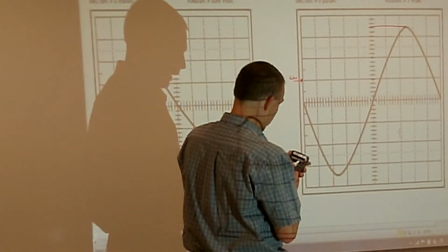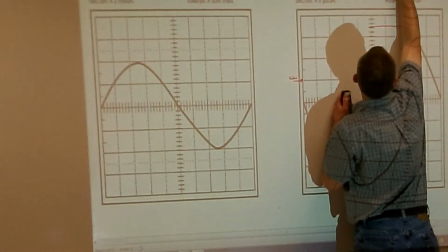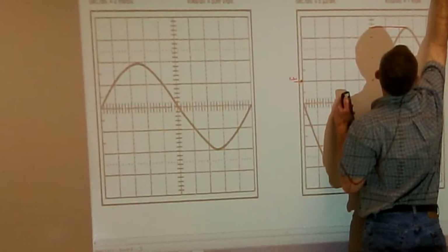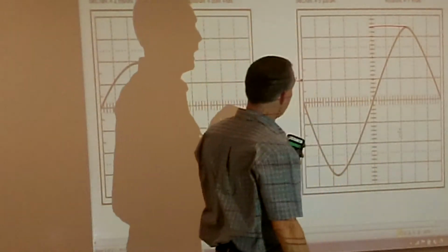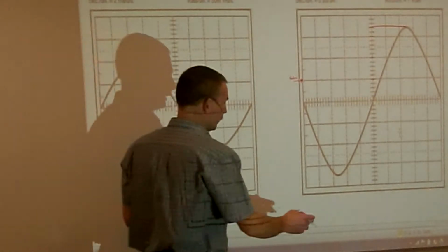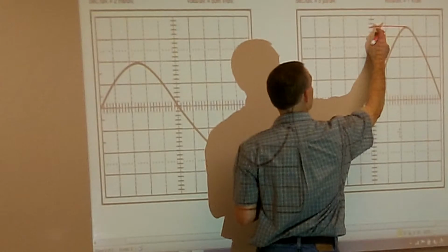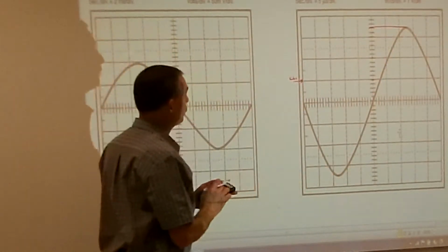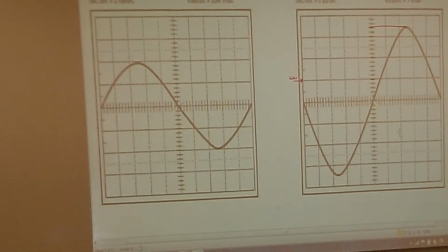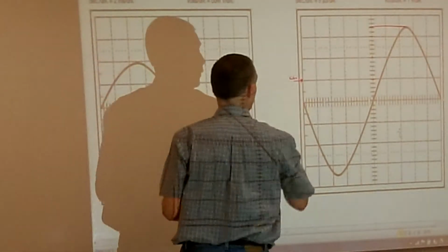So what I would do is put in my 2.4 times how many volts per division I have. For example, the 1 volt times 2.4 would give me my Vmax equal to 2.4 volts. That would be what my Vmax is. Okay? So each subdivision would be equal to 0.2, so I just count them as 2, then 0.2, 0.4. And then I just multiply it by what the volts per division is. So what would be my DC offset if I had my 0 point right here?